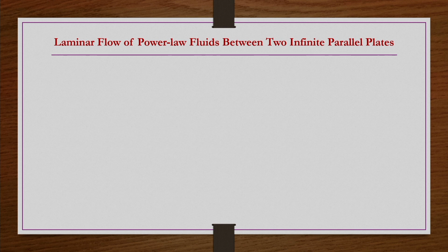Whether it is a power law fluid or a Bingham plastic fluid, as long as the flow is laminar, symmetric and one dimensional, we can simplify the momentum equations in the same way. Up to getting the relation for the shear stress, we are not incorporating any information about the rheology of the fluid, so till that point the methodology is the same.